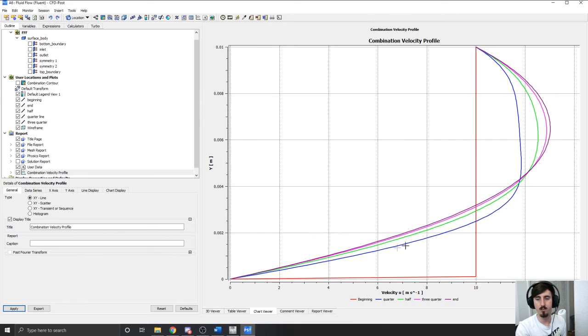So in this case, in a Couette flow, it's more linear because that top plate, as it travels, the friction from the top plate, or the fluid friction from the top plate, is going to create almost a linear velocity of that fluid.